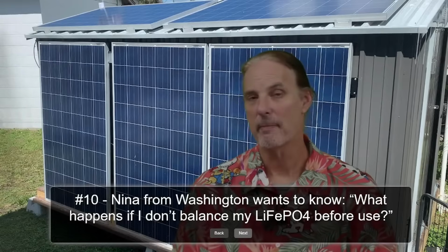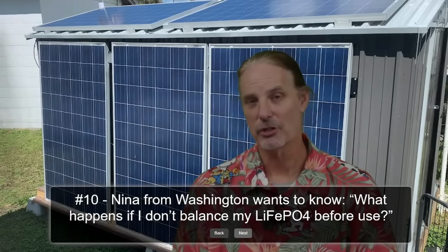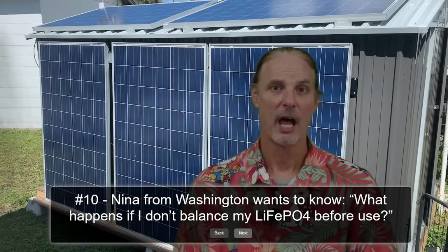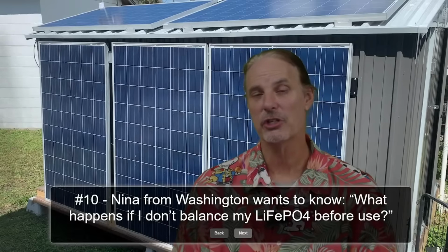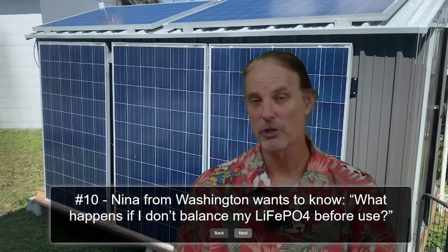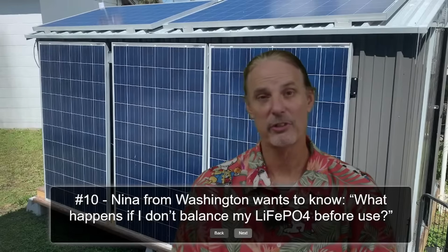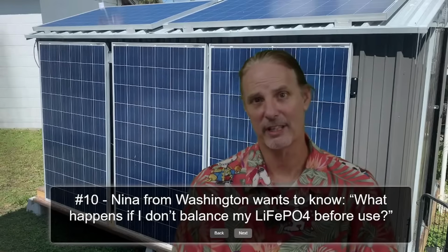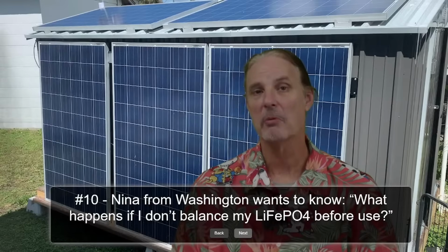You would plug it in, it would come at approximately 50% charge, and you could charge it up with the system. As a matter of fact, that's what I did with my LiFePO4 batteries when they came in. I hooked all 4 of them up, they were all within 1% of each other. I connected all 4 in parallel and did my initial charge and balance from the 6000 all-in-one with the inverter turned off, so that all the power from the solar just went straight to the batteries and got them charged and reset. So in most cases, probably nothing.